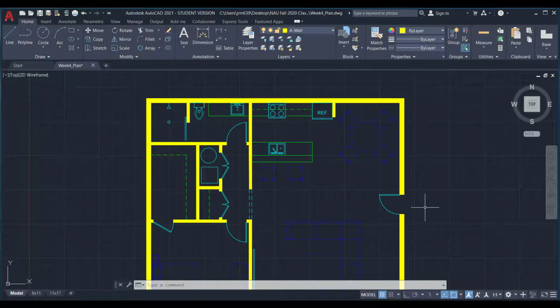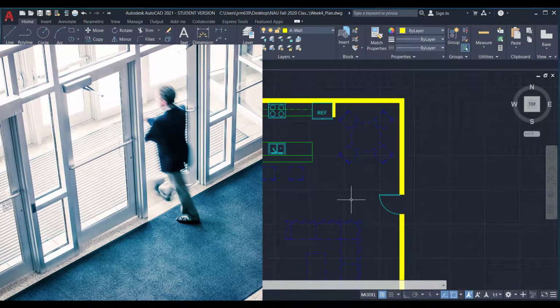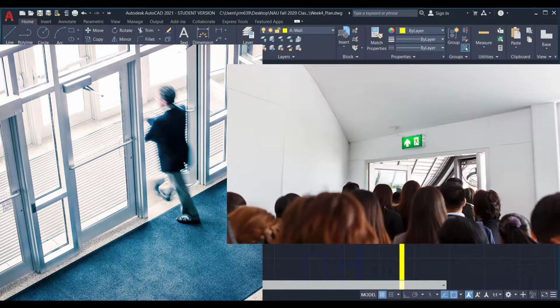Now in a commercial space like a restaurant or hotel, most of the doors that swing are actually facing outside. They swing to the outside, and the reason why is if we had 100 people in this room and all of a sudden there's a fire and they go running, there's going to be a stampede. And it's really hard to open a door that swings to the inside when there's 100 people pushing to keep it closed. So, because of fire safety, most commercial buildings will have it where like offices, exam rooms, anywhere where there's a lot of people, the doors will actually swing so that it will allow people to exit easier.